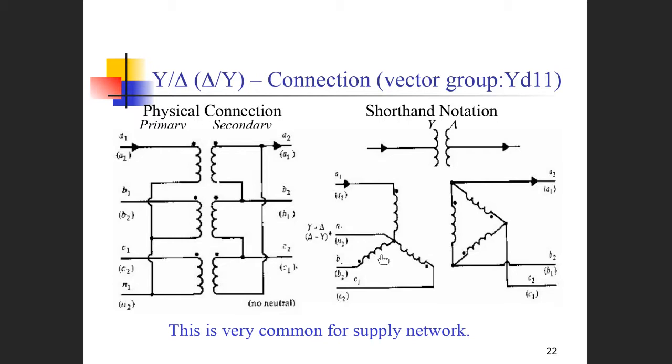Such harmonics can be minimized with delta connections like this. So the delta connection on the high voltage side can minimize the harmonic impacts. From this point of view, such a connection can cancel the harmonics from the loading side to the system. Once again, this is just one type of star-delta connection.